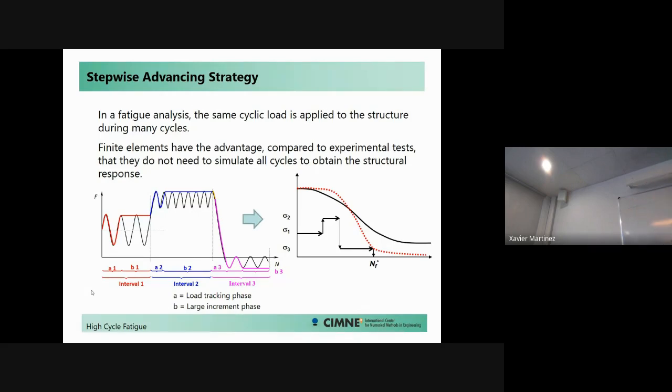When we are in the elastic domain, there is no propagation of crack, there is no nonlinear dissipation inside our model. And how did we do that? Well, we devised a stepwise advancing strategy, which is actually a strategy for us to do these blocks of cycles, these jumps of blocks of cycles.